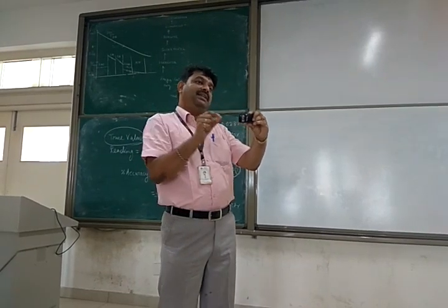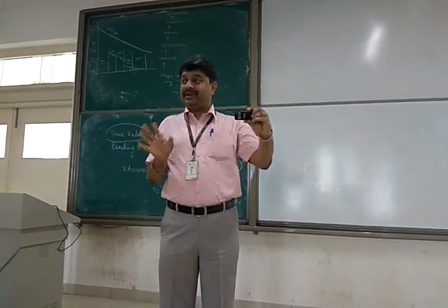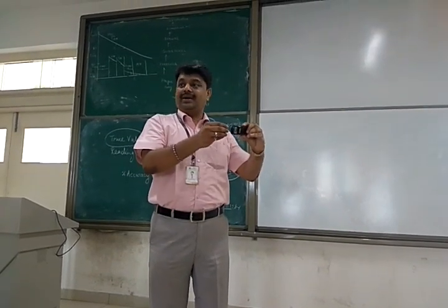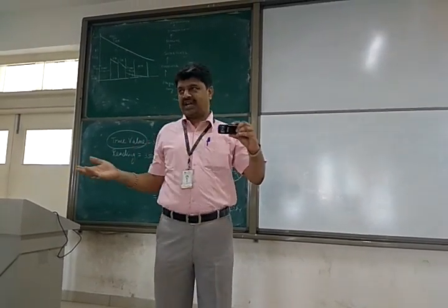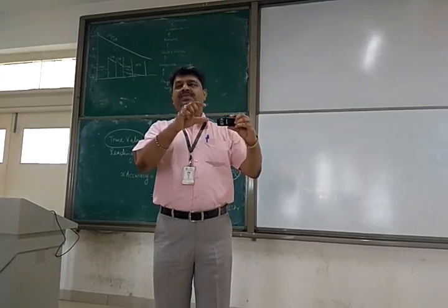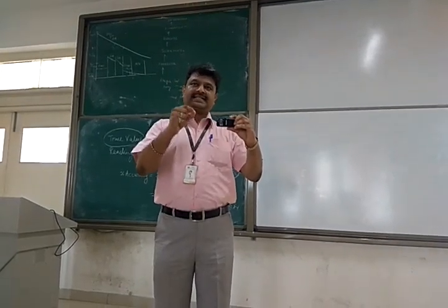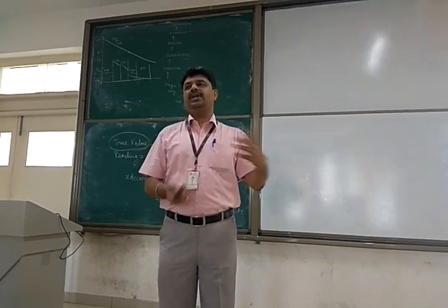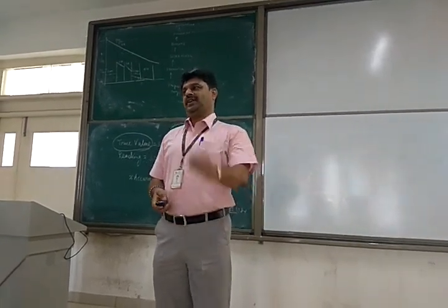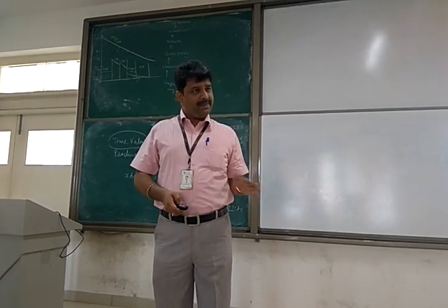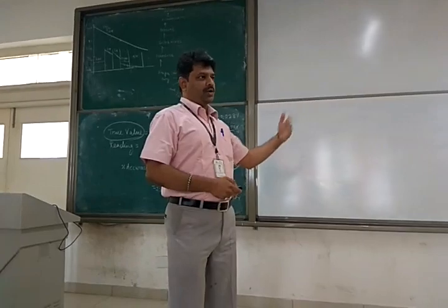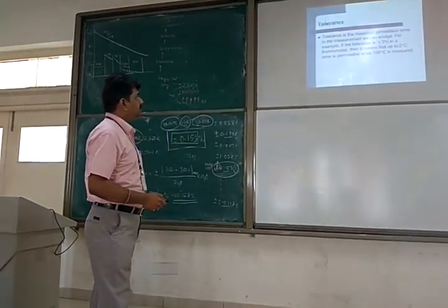That was the number that we assign. I am not computing it from readings. I am just assigning that number based on my experience and the standards guidelines. The number which tells the maximum deviation that is permissible during the manufacturing process is called tolerance. Many people confuse tolerance and accuracy, so we just want to bring clarity.